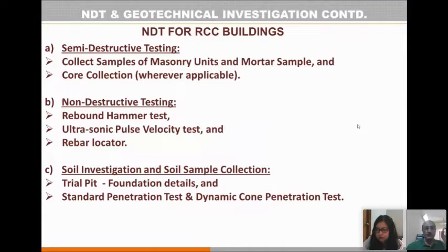So believe the data which you get from the concrete core cutting test. In addition, there are other tests, which are the ultrasonic pulse velocity and rebar locators. The rebar locator test is also very important to reassure that whatever detailing has been given in the drawing has been implemented in execution.